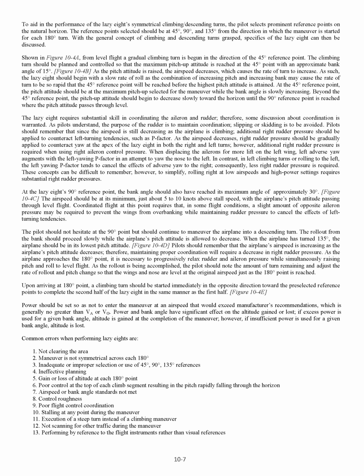To aid in the performance of the Lazy 8's symmetrical climbing/descending turns, the pilot selects prominent reference points on the natural horizon. The reference points selected should be at 45 degrees, 90 degrees, and 135 degrees from the direction in which the maneuver is started for each 180 degrees turn. With the general concept of climbing and descending turns grasped, specifics of the Lazy 8 can then be discussed.